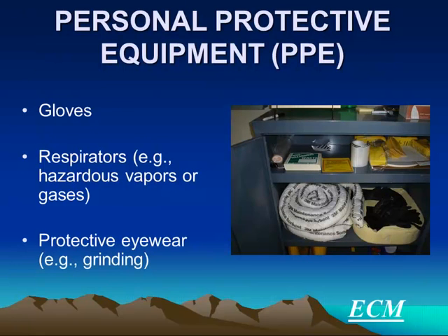Again, by wearing this protective equipment, that's where you're going to avoid those long-term or chronic hazards that you're not going to see right away. Especially if there are any body shop employees, it's really key that you're wearing your respirator properly and that you have a proper fit on it. That's a high point of contact for chemicals for the auto industry, the body shop personnel using those paints. There are some real easy tests to make sure that mask is fitting you, and that should be part of a separate training program for anybody that's using respirators.